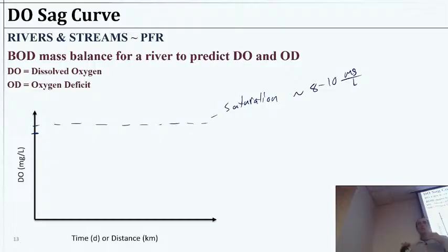In any case, hopefully we've oxygenated our wastewater right before discharging so that we don't have an immediate disruption of the local ecology. Since we've got blowers blowing air into our wastewater anyway, let's send a little bit into the stream right before we send it down the pipe. That is a common practice to re-up the oxygen concentration.